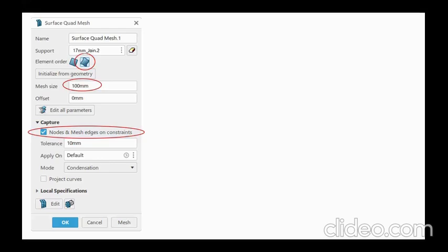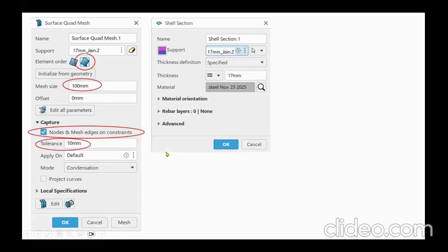I'm going to merge any two nodes which are within 10 millimeters of each other. Now, this did not have to be done in tutorial 12 of the buckling, because I joined the whole thing and then meshed it. But anyway, here I have to do that.